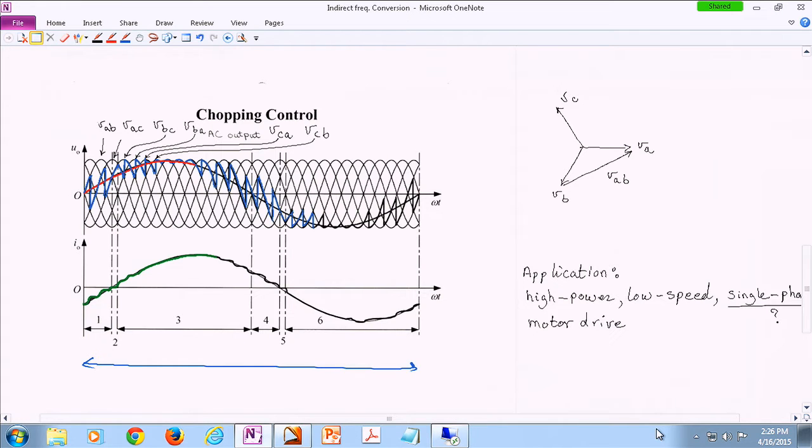Now, if you are worried about these sudden jumps in the output voltage, like over here, it depends on what kind of quality of output voltage waveform you want. There are transformers that are called phase shift transformers. So it's like a delta-Y kind of combination, one of the power system tricks, and you can actually use those transformers to create 12 phases rather than 6 phases.